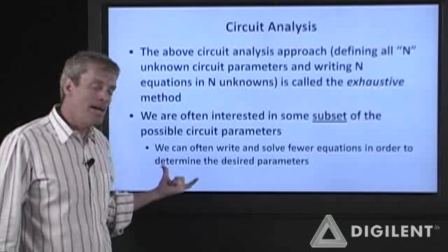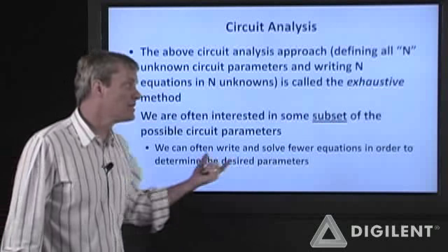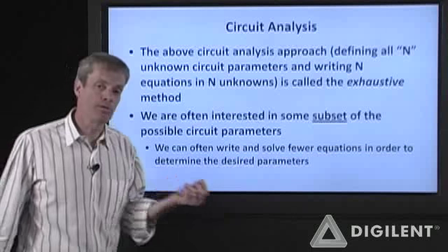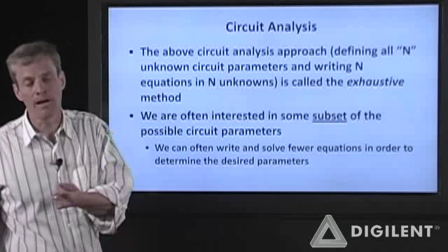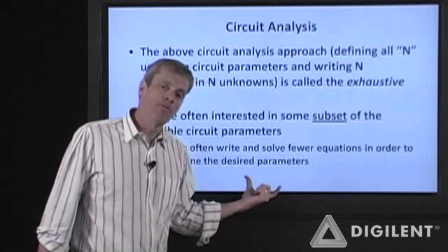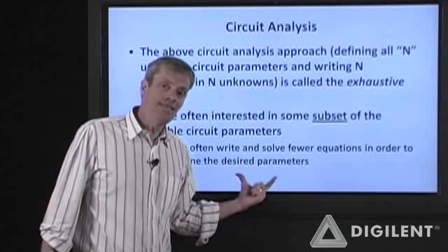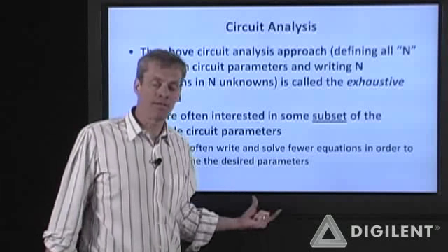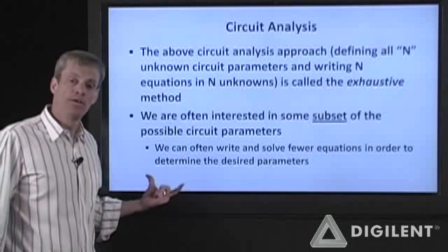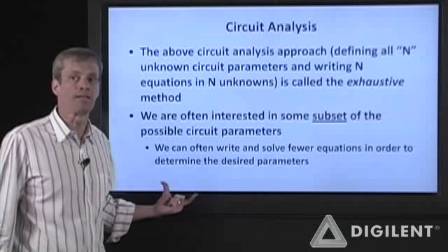However, sometimes it's not necessary to go through every single one of these steps. If we're interested in some subset of the circuit parameters, maybe a particular voltage, a particular current, the power dissipation in a particular element, we may be able to get by with writing and solving fewer equations. So in many cases, sitting there and staring at the circuit for a few minutes and deciding what to do that will make your solution efficient is time that is extremely well spent.